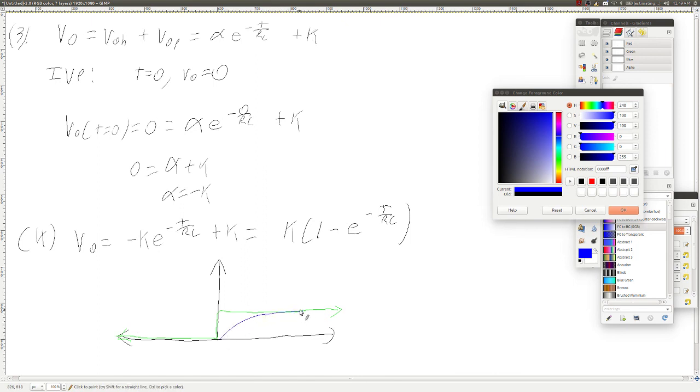This convergence from 0 towards the value is called exponential decay. What's happening is that as the capacitor builds up charge, the current into the capacitor is decreasing because the voltage difference from V in to V out has decreased. That means that as time goes on, current drops, so the rate of charge decreases, and you slowly converge to the value that you want.